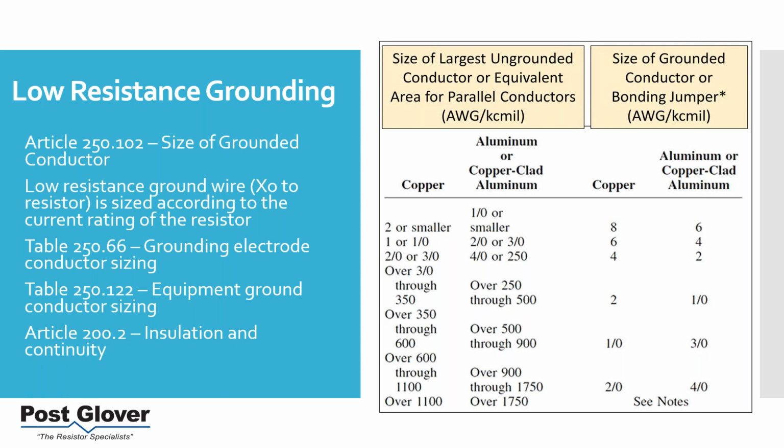It needs to be fully insulated for the neutral current. And then the continuity is essentially making sure that you're safely connecting. You don't want equipment ground to be a part of your system ground. If you have a system fault, you don't want that cabinet being energized. So that's basically what that section is about.